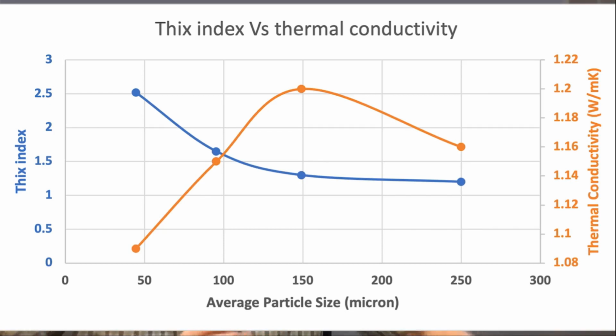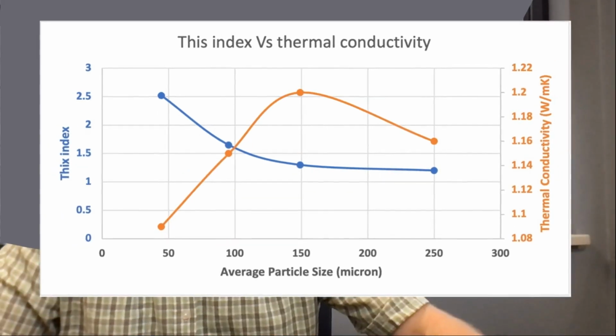So if you take nothing else from this presentation, understand that particle size distribution, and optimizing particle size distribution, is really important when you're trying to optimize thermal conductivity and viscosity.